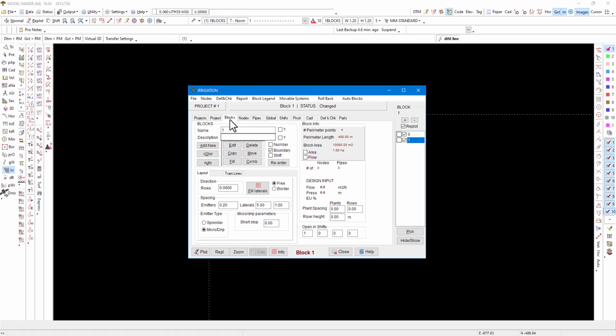And then we're going to look at the tramline option. So in this case, this needs to be 0. I'm going to keep my general distance as 5 meters, and there's two ways to approach this. So I'm going to go and say tram lines, and I'm going to say there's one extra. So it essentially does the same thing, but we are saying that the general distance is 5 meters, and we want to add one more line that is 1 meter away. Let's see what that does.